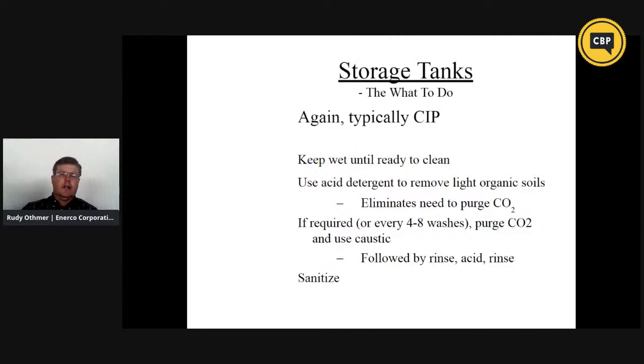It can be a fairly violent reaction. So purge your CO2 if you do have to use an alkaline cleaner in the storage tank. And then even if you're just using acid detergent, rinse afterwards, followed by your sanitizing step.